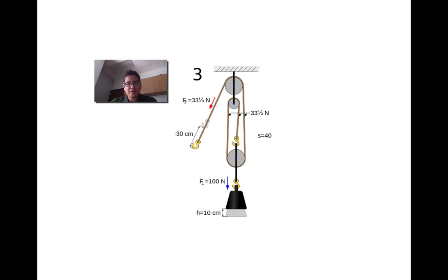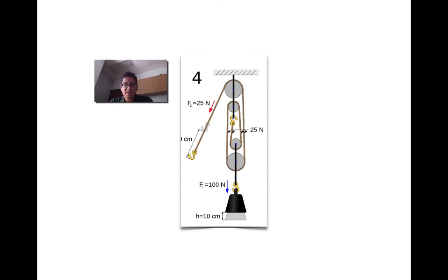Now we're assuming here that none of the force is being leaked out or wasted on friction. The friction points for this mechanism would be the pulleys themselves, because as the pulleys turn, they can rub metal with metal, or also where the rope comes in contact with the pulley. These two points are where friction can be created, and some of the force that you apply can leak out that way, requiring you to pull a little bit more than just a third of the force.